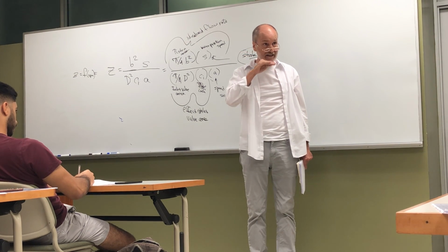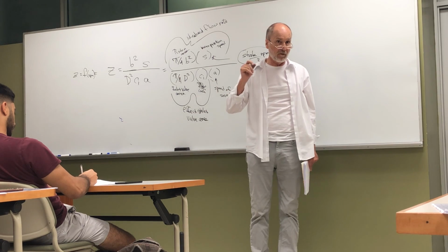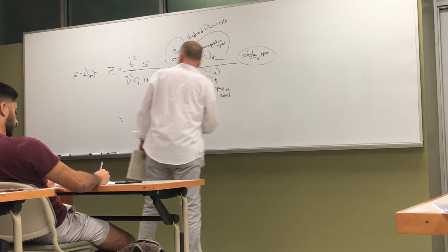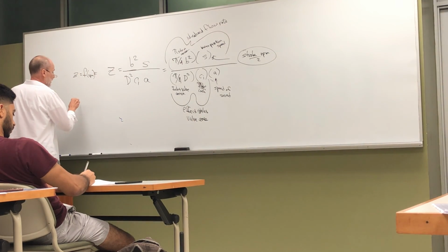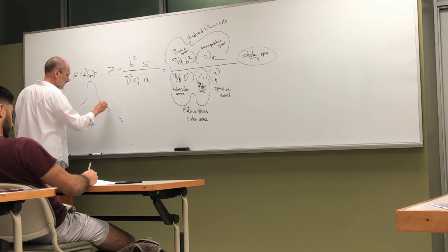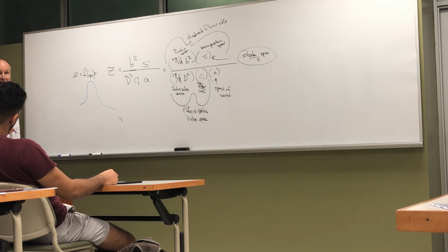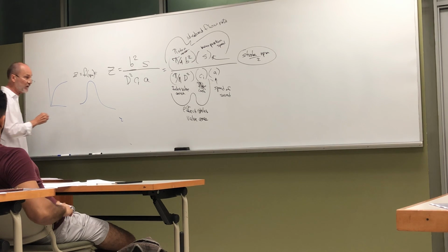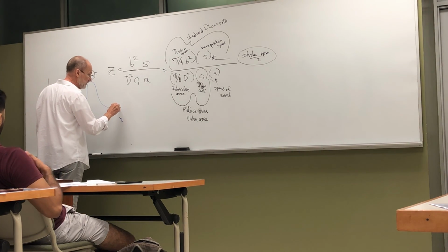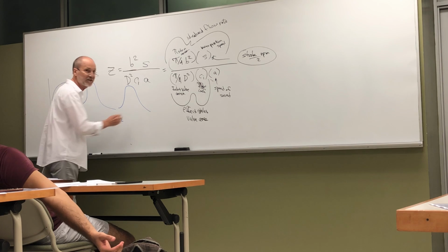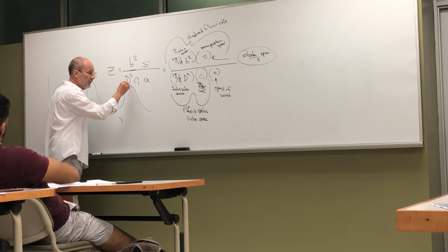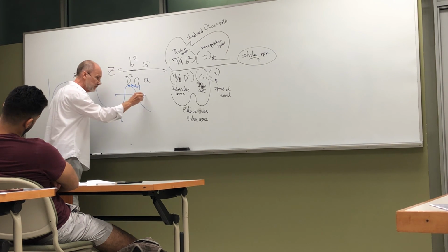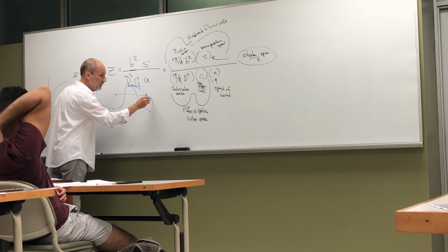If it was constant Mach index 0.5, we wouldn't have any problem at all. If it was Mach 0.5 the whole intake stroke. But remember, the valve goes, its lift versus crank angle looks like that, and the flow coefficient looks like this. So if I do a cross plot, I'm going to end up with flow coefficient versus crank angle that looks like this. At the very top here, we hit Mach 1, but the average is more like Mach 0.5.